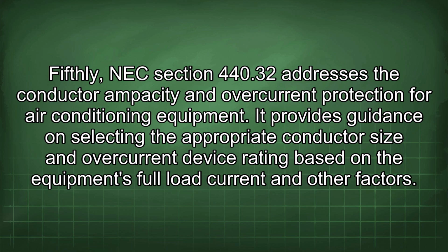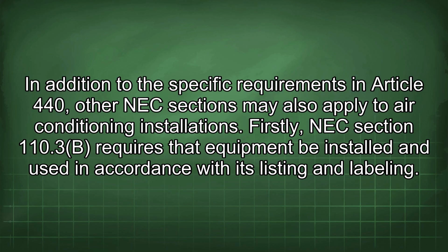Fifthly, NEC Section 440.32 addresses the conductor ampacity and overcurrent protection for air conditioning equipment. It provides guidance on selecting the appropriate conductor size and overcurrent device rating based on the equipment's full load current and other factors.